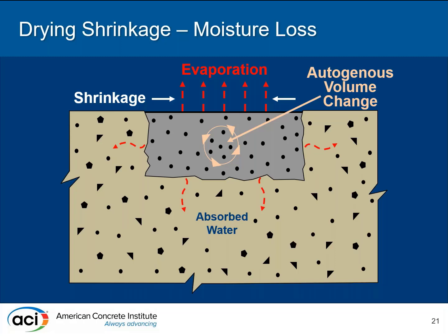Ideally your new material doesn't shrink way more than your existing concrete. So you often want a low shrinkage material, and these are the things the code requires you to think about in how these are going to work together. It does acknowledge, or you should be aware, that no shrinkage is not really a realistic thing, especially for large quantity repairs. So you need to think about bond, which I'll touch on a little later, but none of these things happen in isolation.